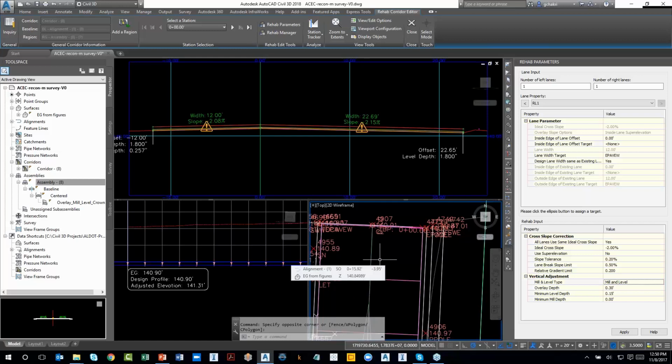Like one of the reports that I was showing, I can actually get the profile off of this process and create a design profile out of this particular corridor, and I can use the existing best fit profile tools on that object to smoothen it up. So that way you are actually getting a best fit alignment and a best fit profile. That's one way to do that.